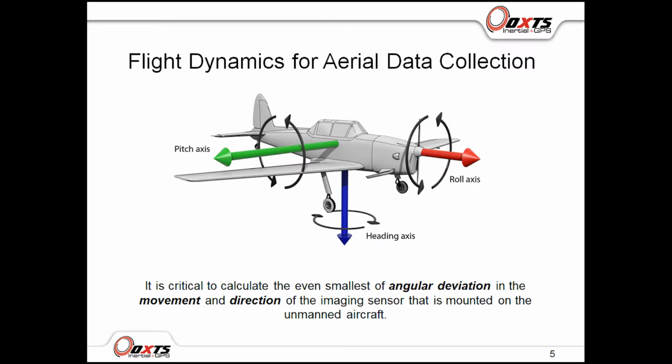These ground control points will be marked with targets that will be seen in the aerial platform flying overhead. Once a flight is performed, the mapping technician will identify the ground control points in the images taken by the mapping sensor. This will assign the corresponding pixel in the image with the known X, Y, and Z coordinate of the corresponding ground control point.